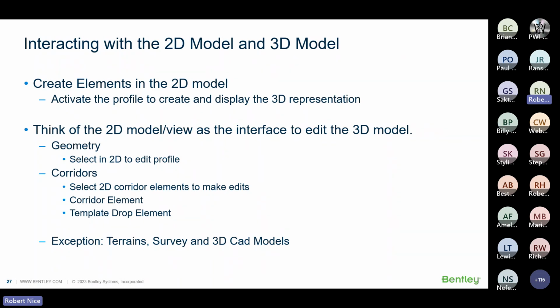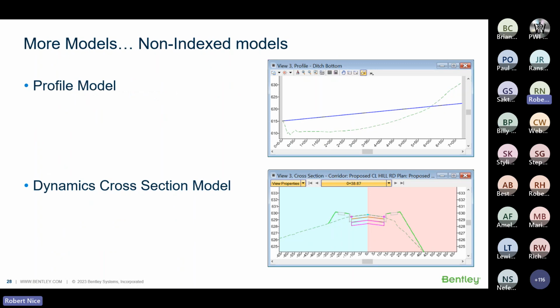And again, that is not a MicroStation fix anymore. It's just now a new model type. So this is a fairly big change from what you're used to. The profile model and the dynamic sections are not the deliverable profiles and cross sections. I call them a design section. So this profile model, which you can put into any view, is your design section. And that is where you place your curves, your spirals, you look at the lifts and lowers and whatever. You bring in other information, you can annotate that information, put in points, bridge deck, whatever. But that is your design.